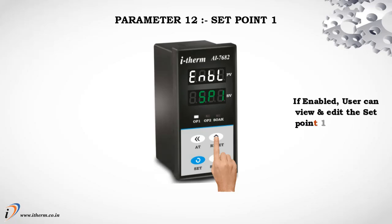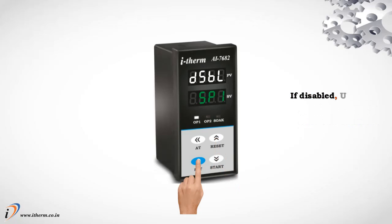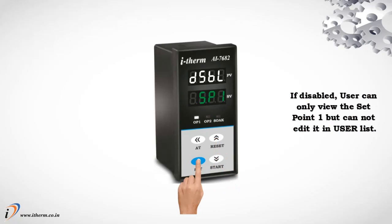Parameter 12, Setpoint 1. If enabled, user can view and edit Setpoint 1 in the user list. If disabled, user can only view Setpoint 1 but cannot edit it in the user list.